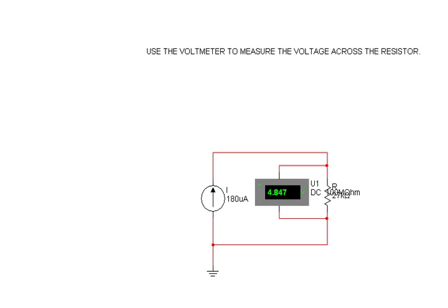Let's stop the simulation, because if you edit anything on the measurement components, it won't change unless you stop the simulation and run it again. Okay, that's very close, 4.859, and the answer from the law is 4.86. So in the lab you can get both these answers according to the resistance of the voltmeter, according to the company you're using. Of course, the companies have different resistances for the voltmeters, that wide difference.